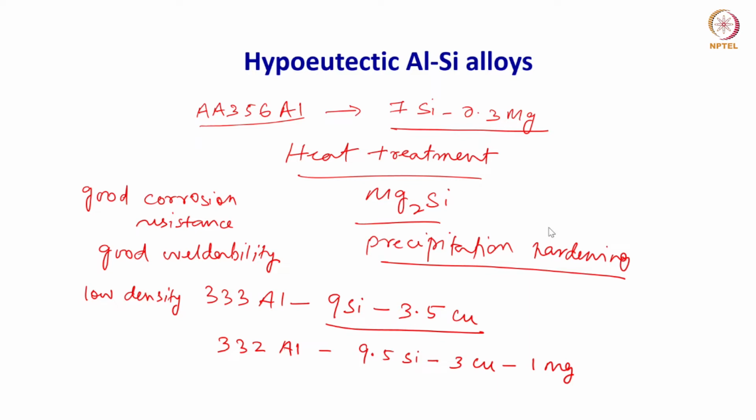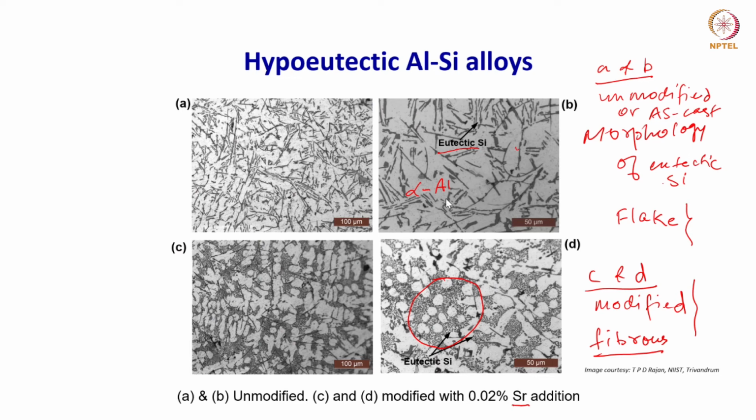You simply need a hard material, that's all, and that is how the cast irons are also used. So as I said in the beginning, it is a cast iron equivalent, not only in terms of the castability, but also some of the properties. And again, silicon comes into the picture for that as well. The presence of silicon in this particular morphology provides the material a very high hardness, which is useful for this kind of application. Even the other application that I was mentioning for the automotive, that is the wheel, does it need resistance against friction and wear?